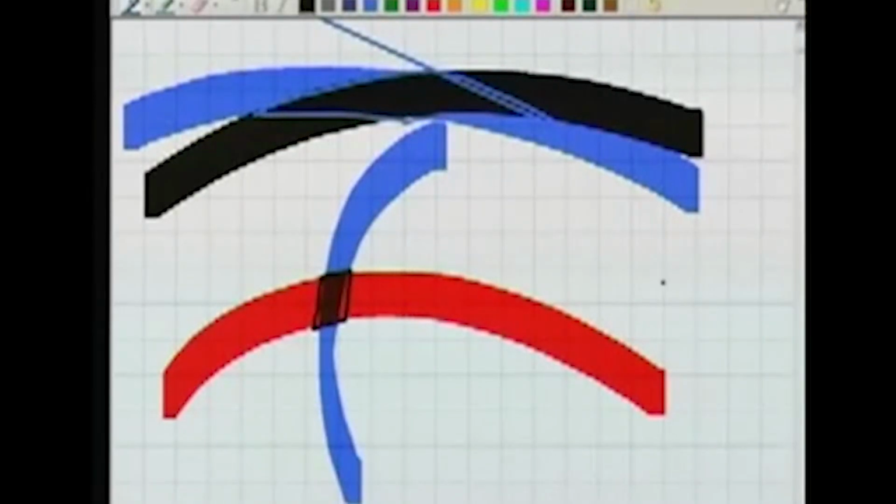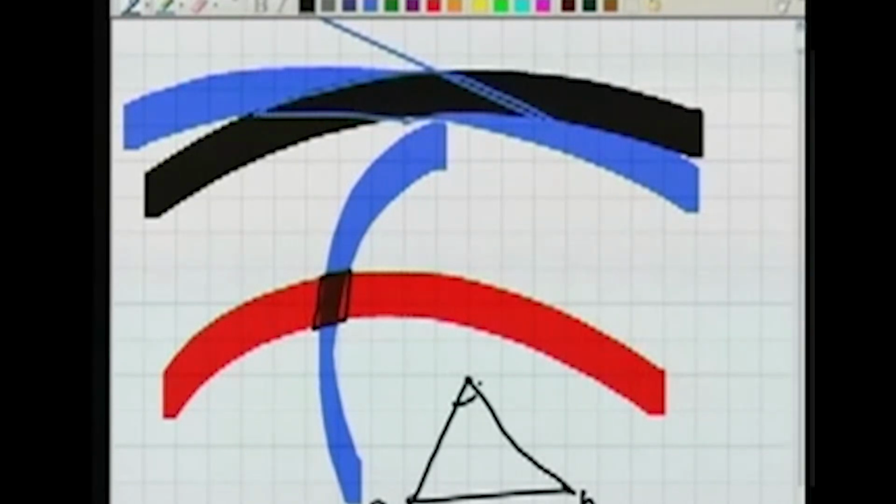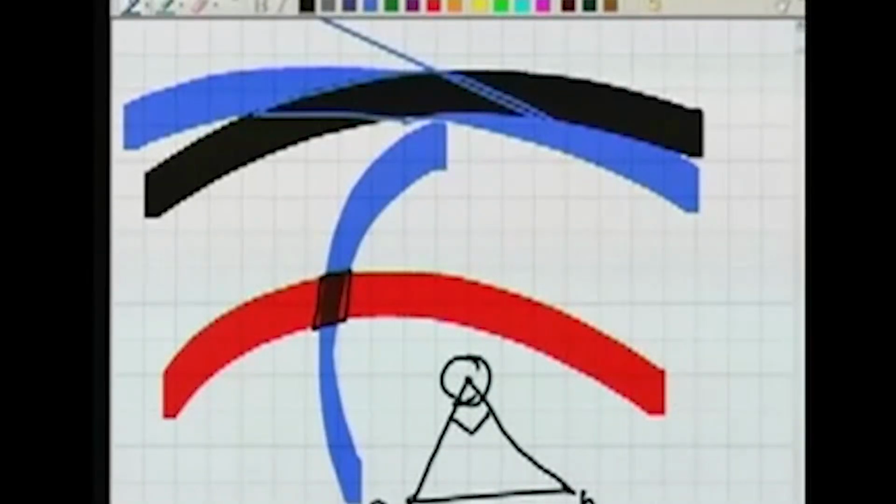So what we found from there, we found that in order to locate, with respect to two known points A and B, a third point C, by this graphical method of drawing the arcs, this point C will be located with good accuracy if this angle is 90 degrees. If this angle is very small or very large, this point will be located now with more error. So what we are going to find is the same thing; the graphical thing was what we did, because we came to the conclusion that this angle should be 90 degrees there.